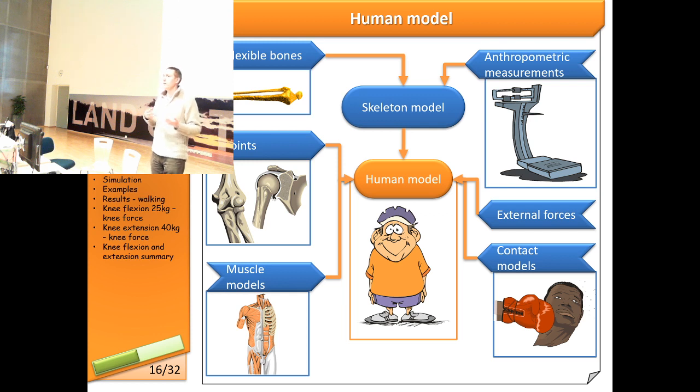But it's not a wheel that we have as a joint, for example, in the knee, it can just rotate a certain amount of angle. Some amount in plus, some amount in minus, and you should not exceed that. So it's good to have some kind of a model. It can be a torsional spring that increases the stiffness non-linearly when you reach the limit, and that's how you can model in simulation that there's a limit and you cannot pass it. Or you can use some other tricks depending on the simulation software that you're using.